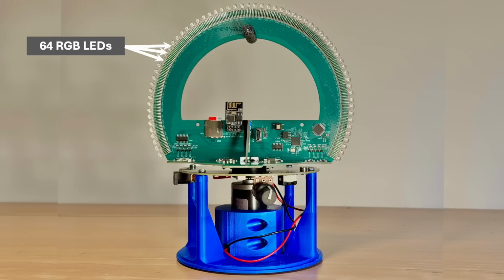The 64 LEDs are mounted around the outer edge of the LED board. This means they emit light within the image plane to the left, to the right, or upward. That's also why I didn't use surface-mounted LEDs. SMD components would have emitted light perpendicular to the image plane, which wouldn't work for this design.